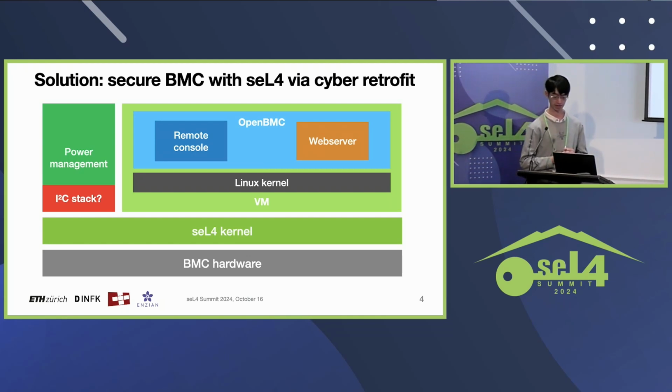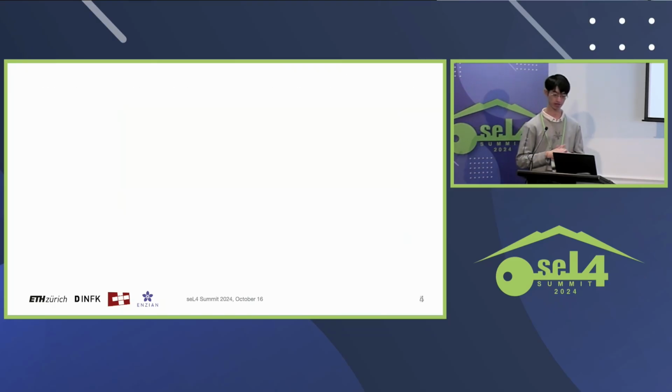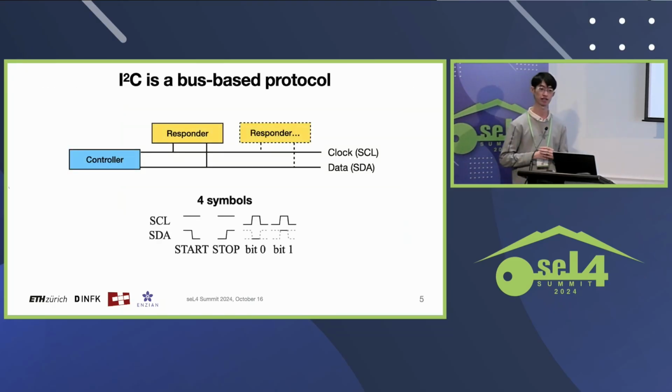a trustworthy I2C stack? And before diving into our approach, here's a bit more background on I2C and why it is different. Well, I2C is a bus-based protocol. It has two wires, a clock, SCL, and a data line, SDA.